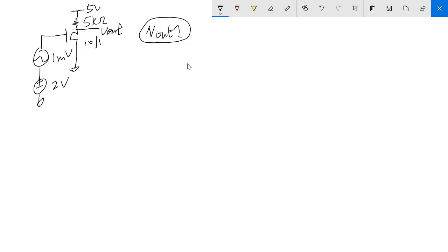So this is pretty interesting. This is a pretty standard example actually. When you have a mixed signal like DC and AC, how can you deal with it? The first step can be a little bit confusing. You are thinking about why we have to do that. It's been confusing people for a while. The way to do that is, when you are only dealing with the AC signal, short all the DC voltages to the ground. So you want to model this as AC only.